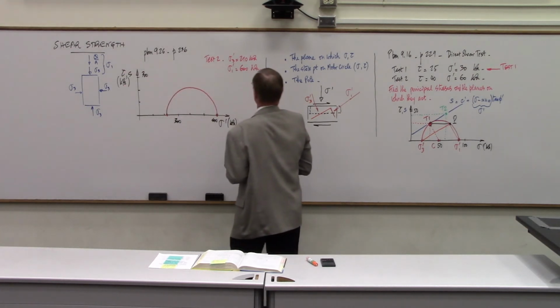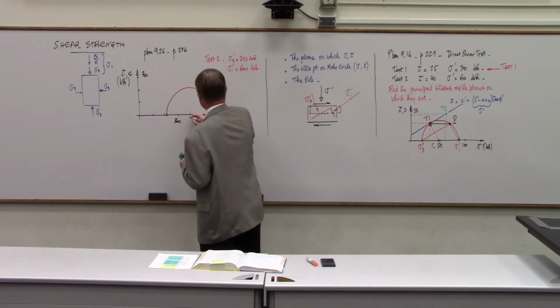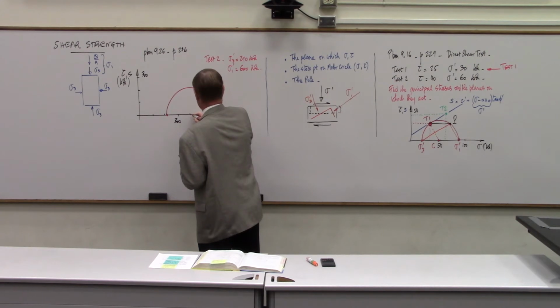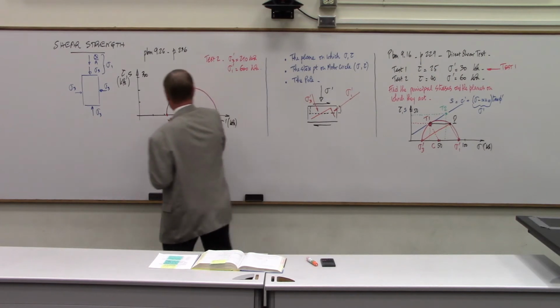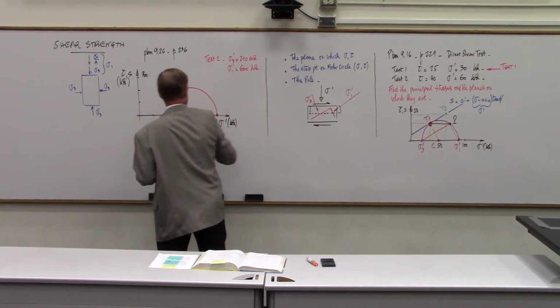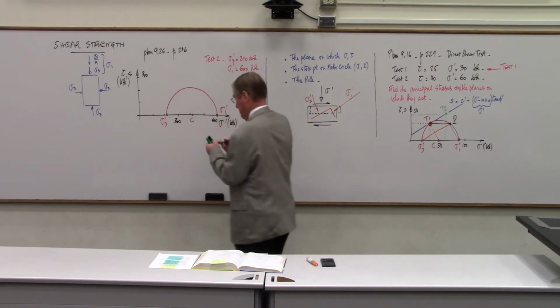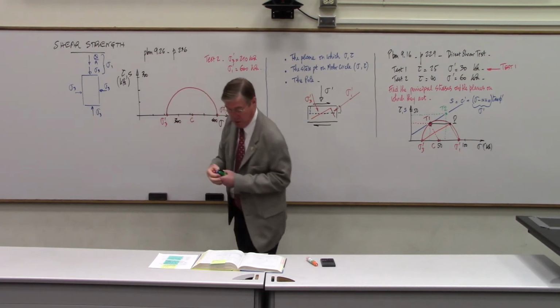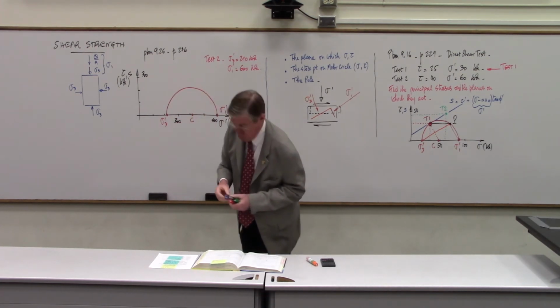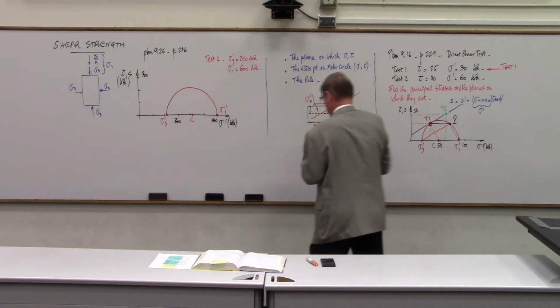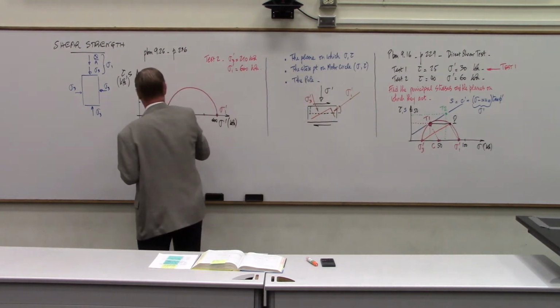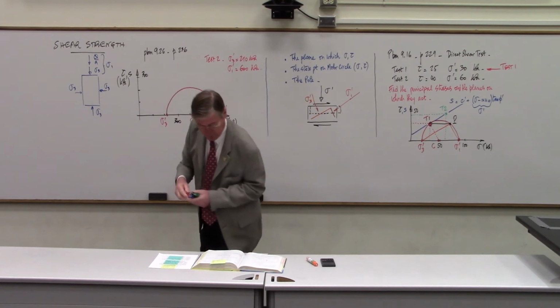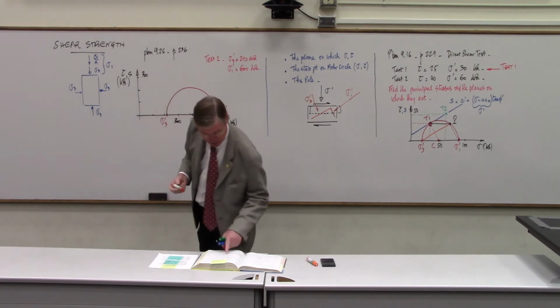And I have a center at 415. So somewhere in here is the center. And then this is sigma prime 3, and this is sigma prime 1. And we had another circle, another test that was here, such that we were able to draw the failure envelope on those two circles. Let me just briefly put the other one in dashed line.